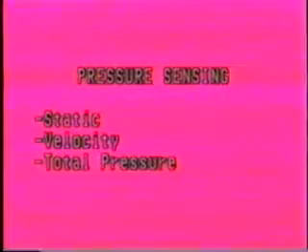Next, let's address the sensing of pressures within the duct using the various types of pressure sensing tips. The accurate sensing of pressures in an all-air system is important when controlling the pressures in a duct. However, to get accurate sensing, certain things must be considered. First, which pressure is being sensed: static, velocity, or total pressure? Then the proper sensing element must be selected and properly located to give the most accurate reading.